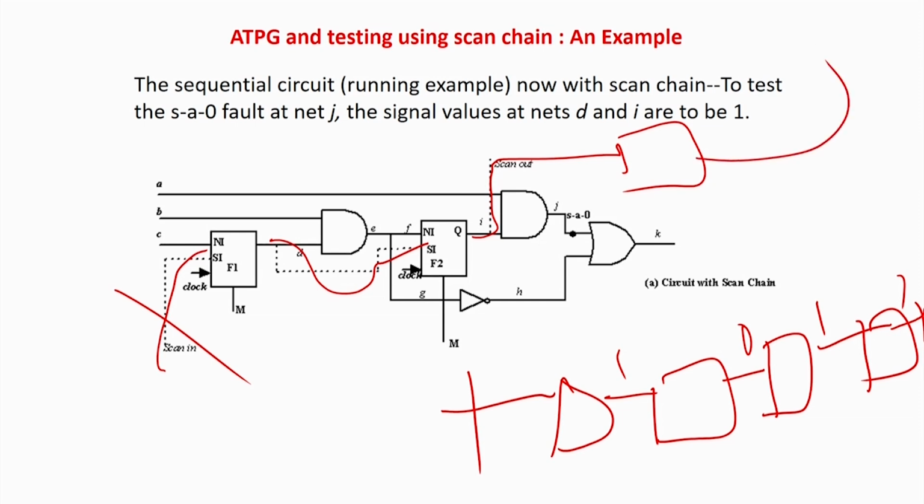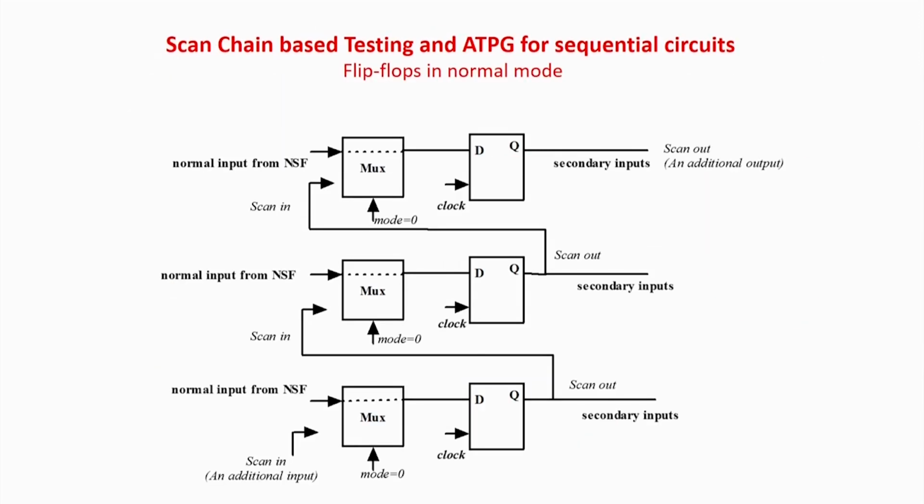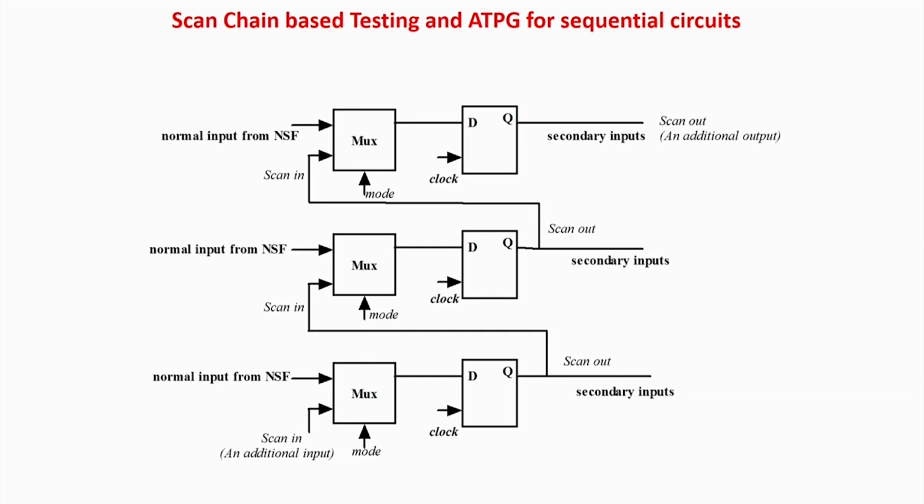So wherever you want to make 1 0 and 1, you can just make this running sequence and load the shift register using the sequence and a clock. That is pure, very simple second year digital fundamentals. You can easily apply this and set the flip flops, and then again bring it back to the normal mode and to the test. I will give you an example to show you very explicitly, but I have just given you the idea.